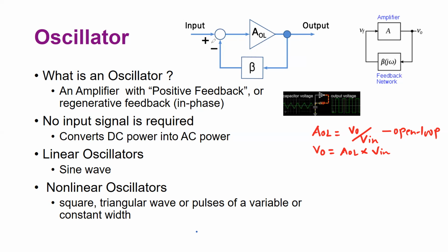We want to modify the input and output impedances so that the amplifier can be driven from any kind of signal source without loading the signal source. And the output impedance can also be modified so that, for example, it can drive any kind of load demanding any amount of current. So that's why we use the feedback.